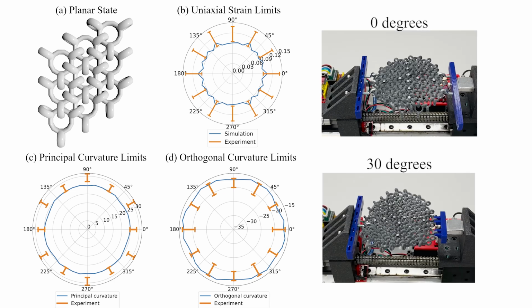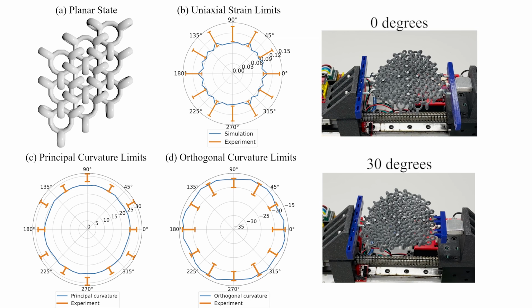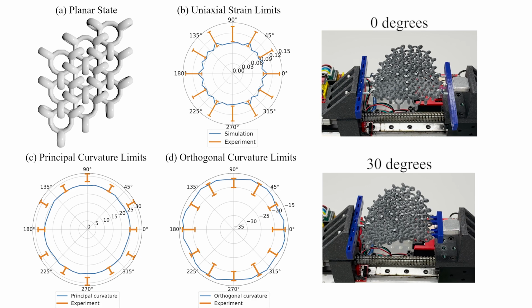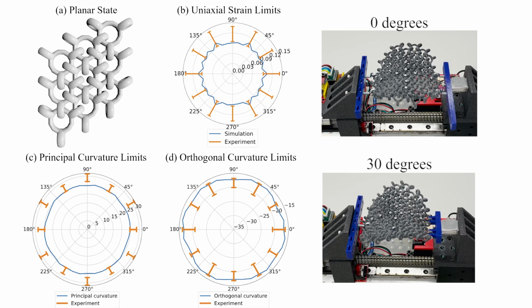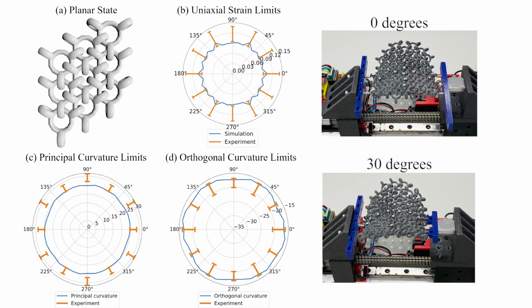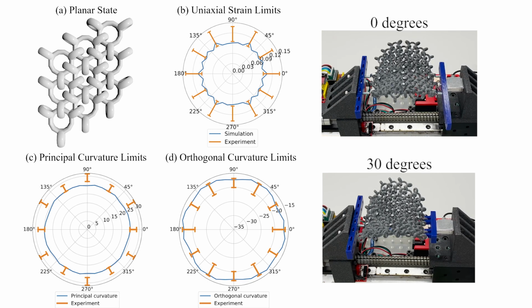Our experimental setup for bending uses a linear stage for controlled deformation and optical marker-based tracking for deformation capture. We load the pre-bent sample in a given direction such as to gradually increase its curvature. We stop once the force sensor signals that a threshold value has been reached, indicating the deformation limit. We then reconstruct the curvature from the captured data. This process is repeated several times for different bending directions. The measured deformation limits are overall in good agreement with our predicted profiles, indicating almost isotropic bending limits for this threefold symmetric structure.